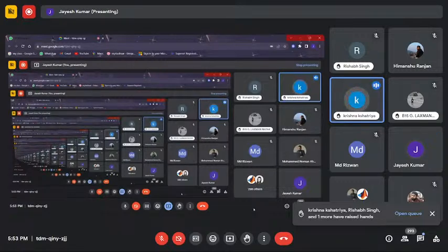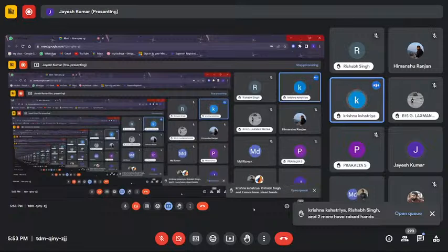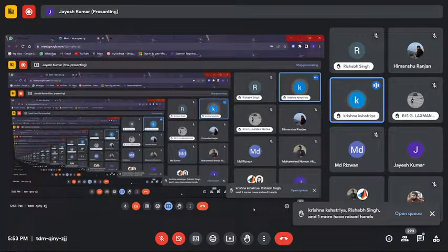My nominal voltage is 28 volt, and the current coming from one string will be 0.5 amperes, because if the cells are connected in series, they give the same current. So the battery's nominal voltage and the panel's nominal voltage should be the same, isn't it?